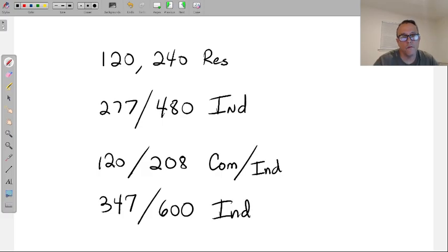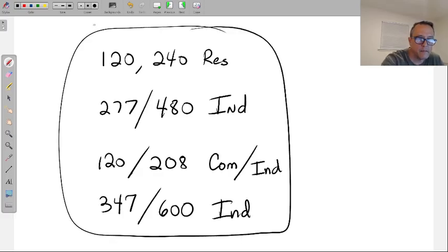These are called nominal voltages, all right? As it says here, conveniently designated for the purpose of. For the purpose of what? Well, when I have to do calculations. If I want to do Ohm's law, I need a voltage number that we're working with. You can say, all right, well, go measure the voltage. Well, what if I'm doing Ohm's law in a building that doesn't exist yet? We're still in the process of design. I can't go measure anything. So I have to use some kind of established number. And so there is where the word nominal will come in.